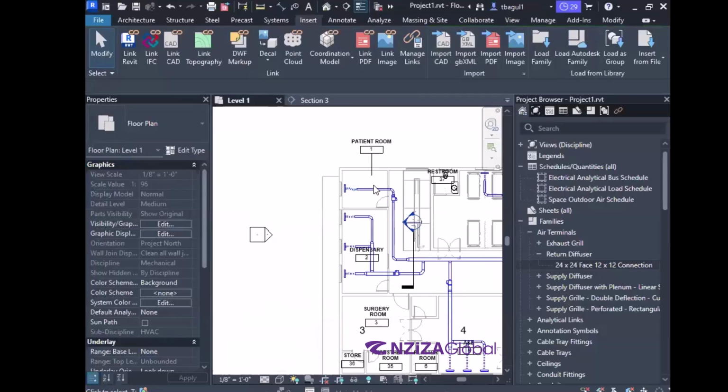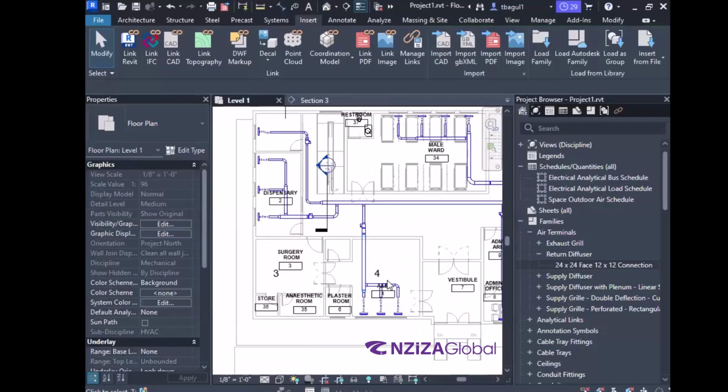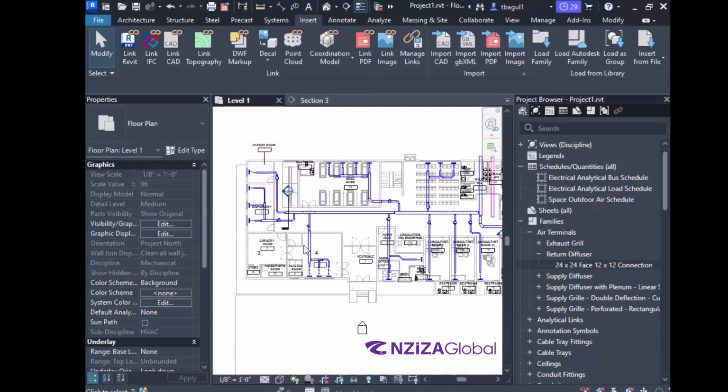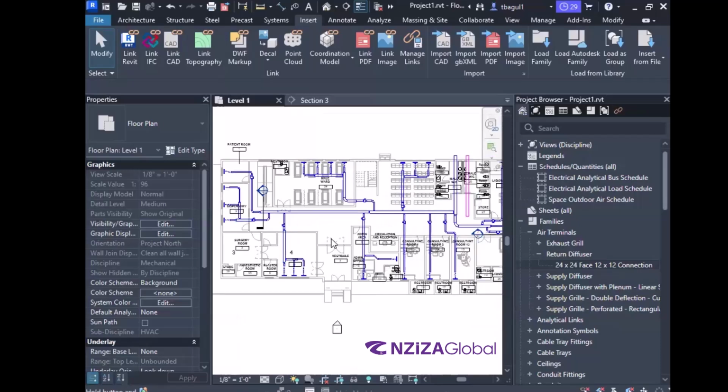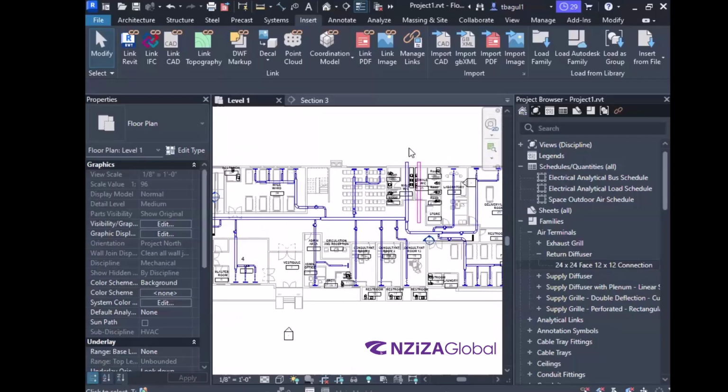For this one, we had calculated it at 85 CFM, right? This one, we are assuming 200 CFM. And this one, we are assuming it to be 500 CFM. A total of 785 CFM. Okay? 785 CFM, again, we are assuming it. We have not calculated the heat load for this one, or this one. Let's consider only these 3 rooms in the project. 785 CFM is going back to the air handler.